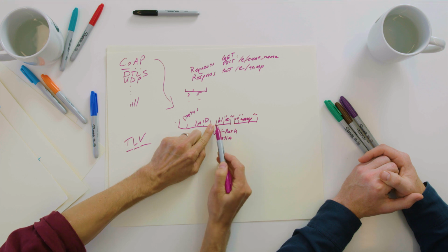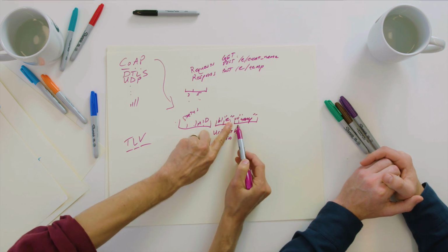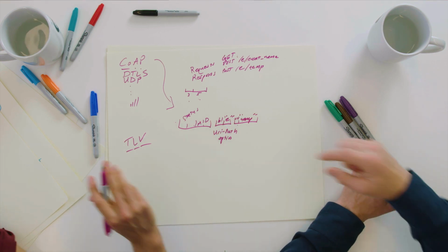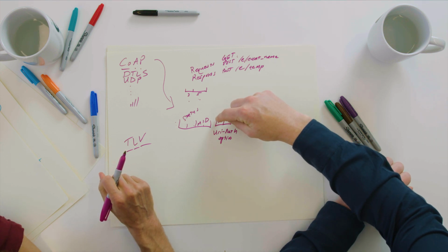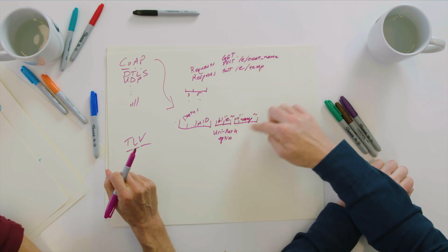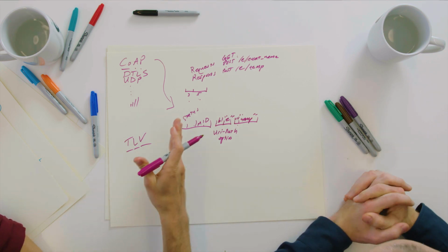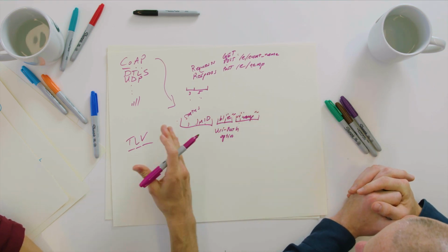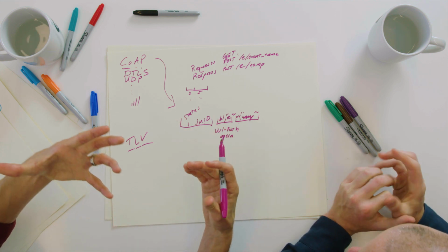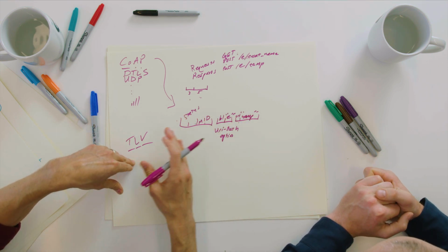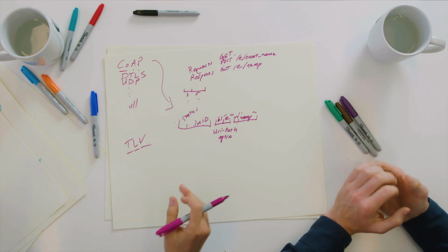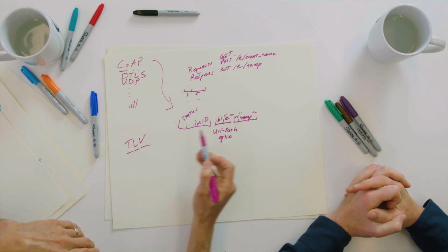There might be some other things in the CoAP message, but in the end, you get a message that's something like 20 bytes that can always be parsed as you're parsing this bit. You only need 2 bytes of memory, and then you can reset, and you can use 4 bytes too. And you can effectively operate on this and discard it to some degree, and then move on. You can keep one little pointer and go through this thing in memory in one pass, and keep on changing state and discarding it as you go through.